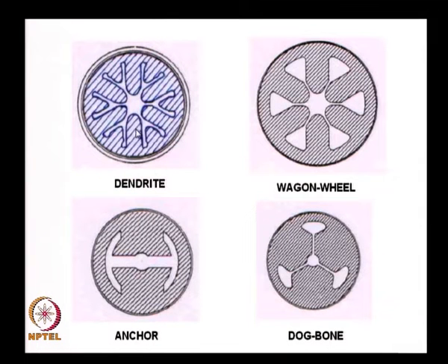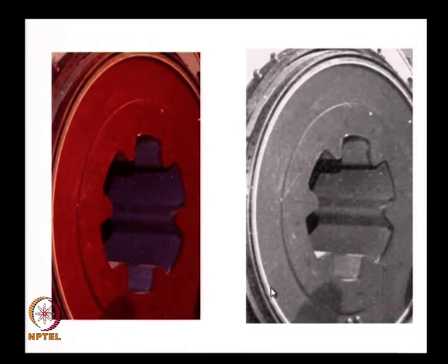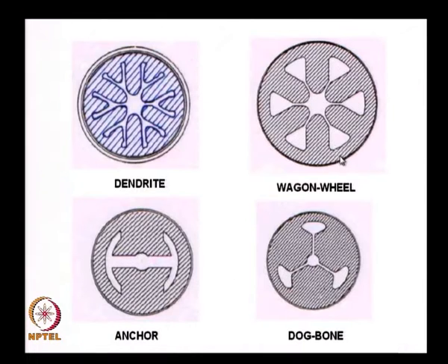Well, the grain surface need not always be a star or a shape like what I just now showed, which is a lobe like this, but it could be any shape. It could be a dendrite. Dendrite is a crystal shape which is like this, and the inner burning surface is something like this to begin with. This is the perimeter into the length of the grain over here, and burning proceeds in this direction. This is known as a dendrite grain.